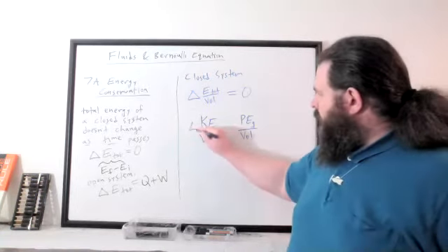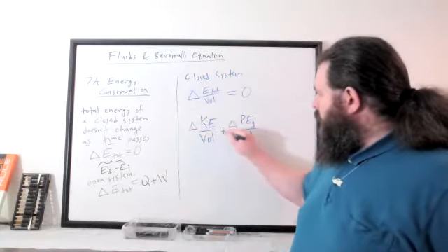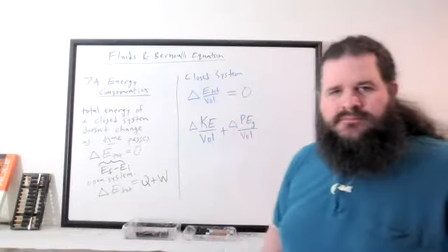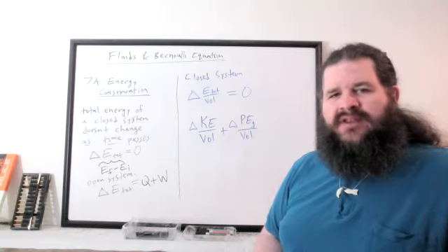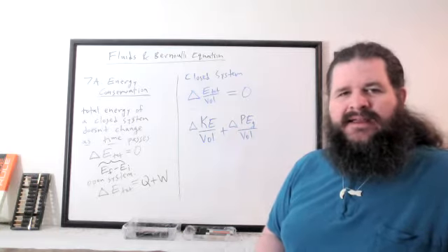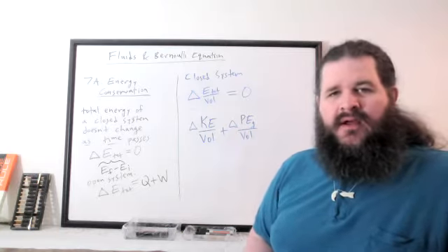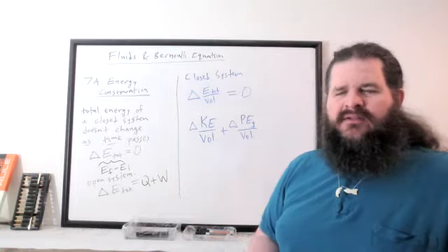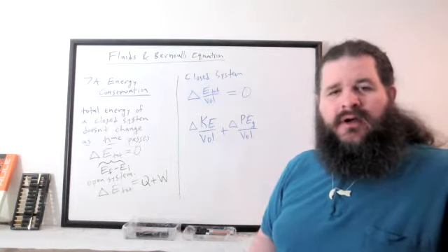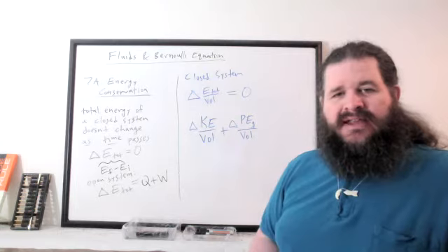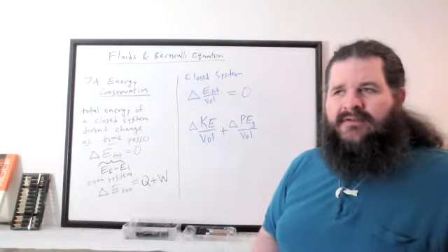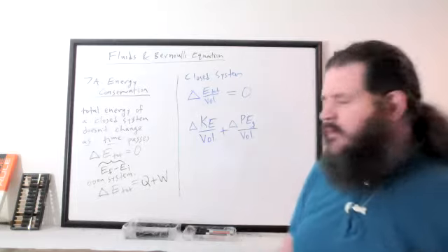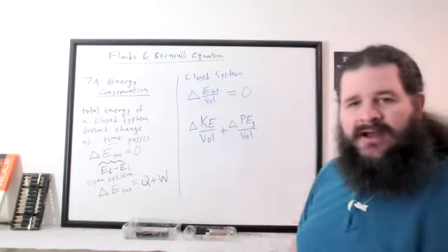And I guess I should put deltas here also. And there could also be thermal energy, but we're generally going to treat that as heat gain or loss. We don't really care what temperature the fluid is. If the fluid is gaining or losing, raising or lowering its temperature, we're just going to treat that as gaining or losing heat. So we'll put that on the other side of the equation if we're dealing with an open system. But let's assume it's a closed system for now.